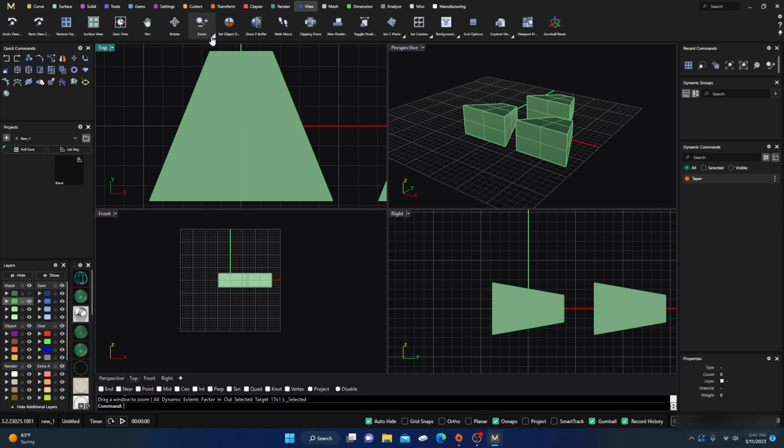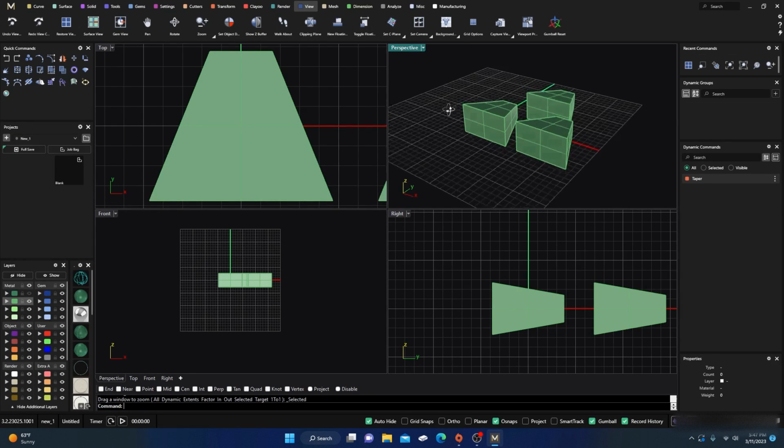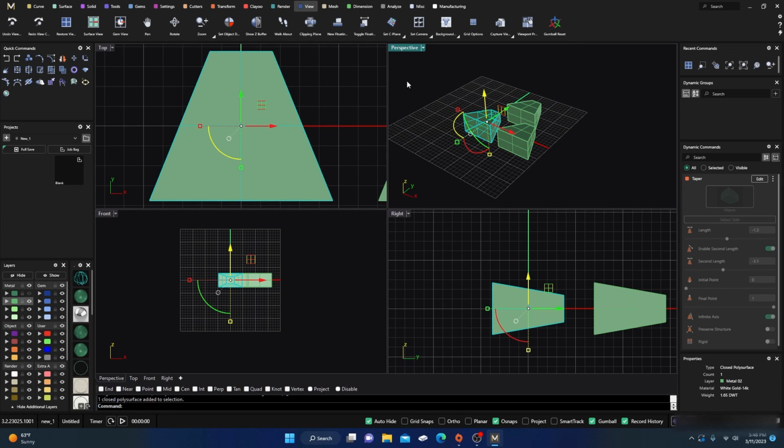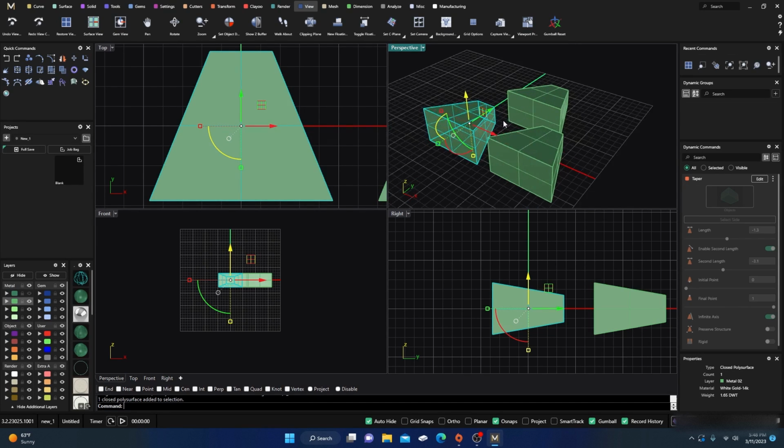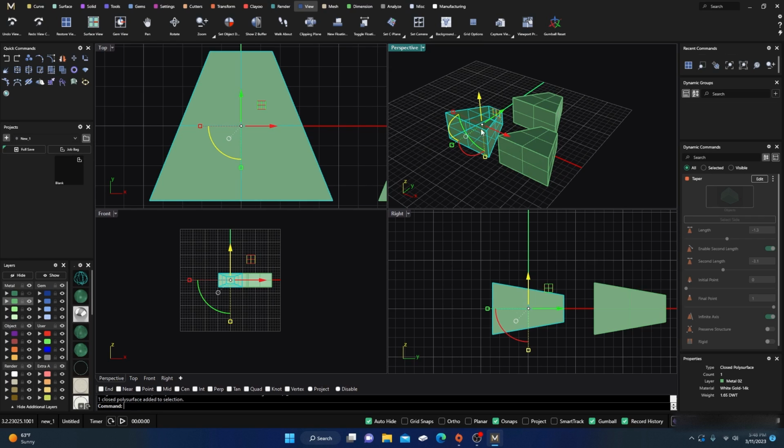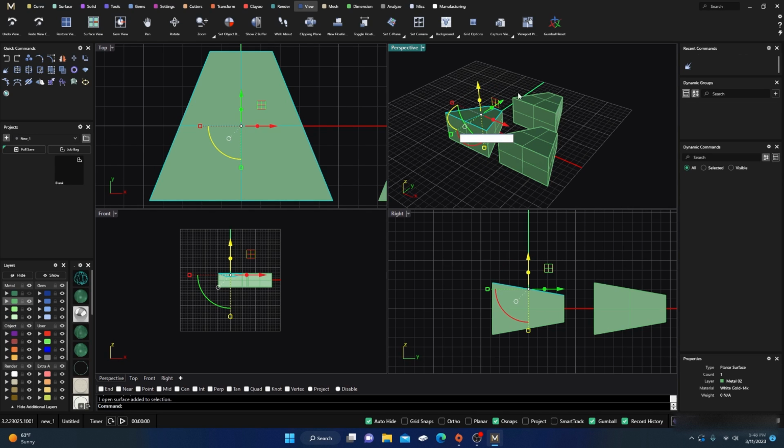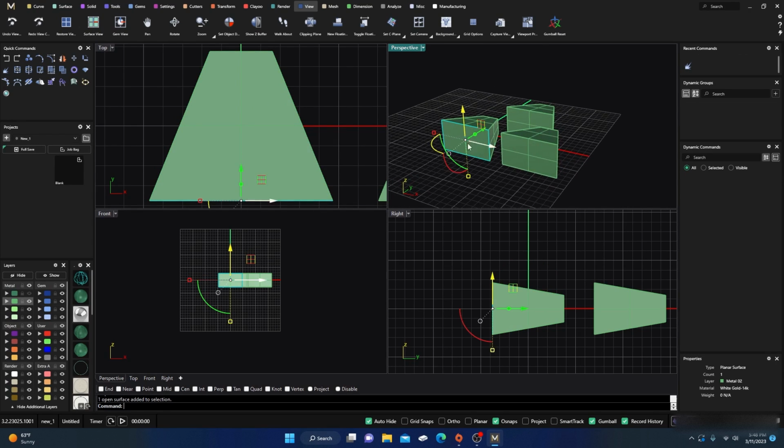All right, and continuing on, selected one-on-one is more for setting up the, we'll talk about that in another video. And naked edges, well, I guess we'll just go ahead. So I'll take one of these, and we haven't talked about it yet, but we need closed, watertight surfaces. So this is a closed, if I look at my properties, it's a closed poly surface, right? But I can explode it. So I just nuked it. So it's in 1, 2, 3, 4, 5, 6 different pieces, perhaps. So if I look at it now, it's just a planar surface, right?